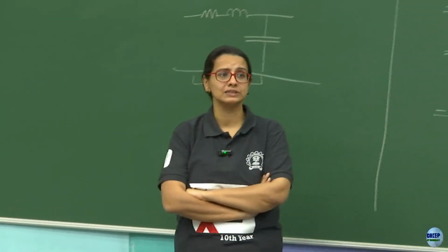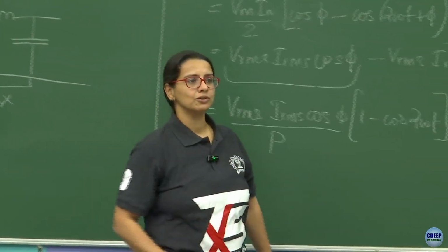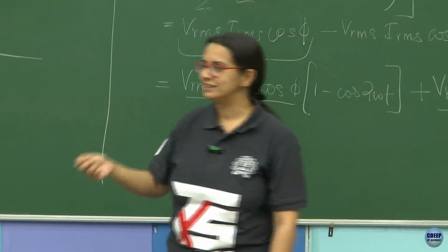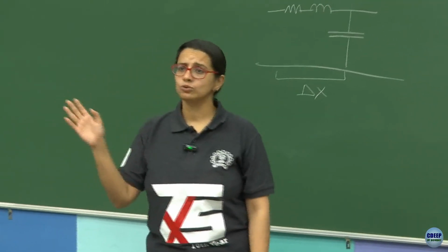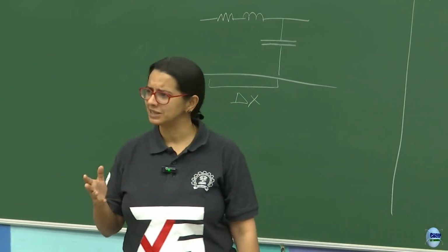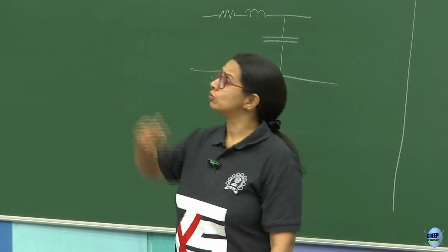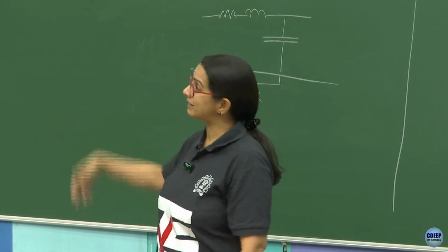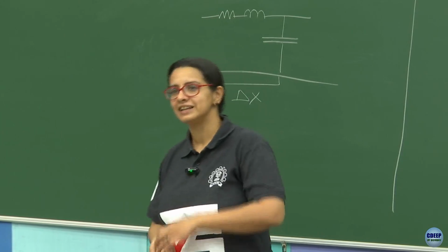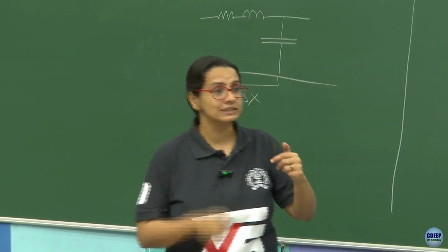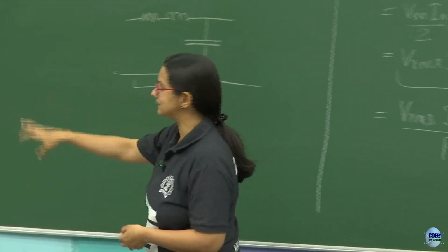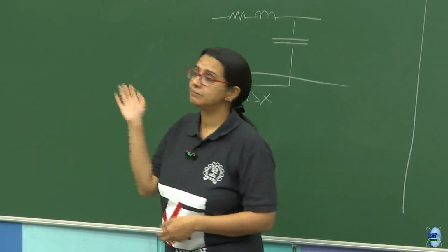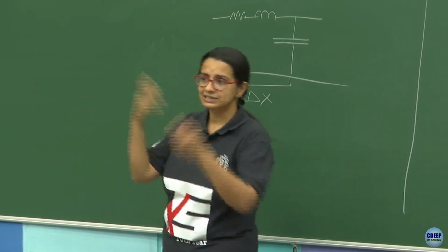Sorry? With some margin of error. Very nice. With some margin of error, I'm not going to go up to Adani and say, "यार क्या 220 का 215 हो गया?" No. But when 220 becomes 200, perhaps I may be concerned. And when 220 becomes 200 very often, when my neighbor also switches on his water heater and somebody else turns on an air conditioner, now I would be really worried, right? So it is the utility's job to make sure that I receive 220 volts as often as possible, independent of how I consume, correct? That's what I sign up for.